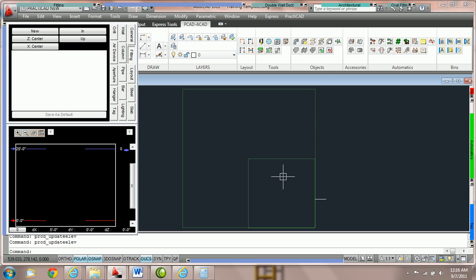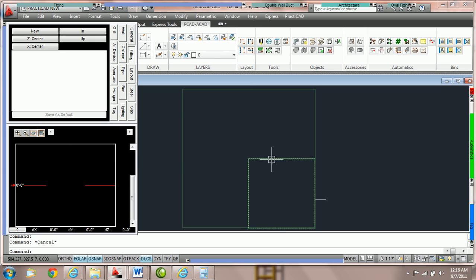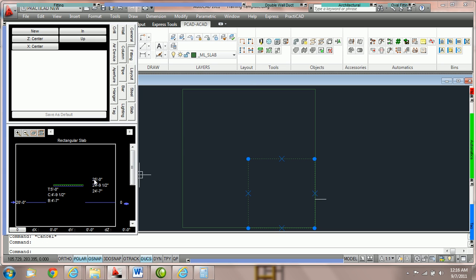The first thing we must do is make sure that both reference points are marked in our elevation box. Currently, we're going to go to the elevation marks view, press the button, and you can see here that we've got the top and bottom. The top we have here is 20 foot. This slab right here, if we click on it, you can see that the top of that slab, it's 20 feet above absolute zero. We have used this as our elevation 0, our relative mark 0, and we've set it to relative bottom. Now what we're going to do is we're going to take the second slab. You can see that the top of that slab is at 25 feet from absolute 0.